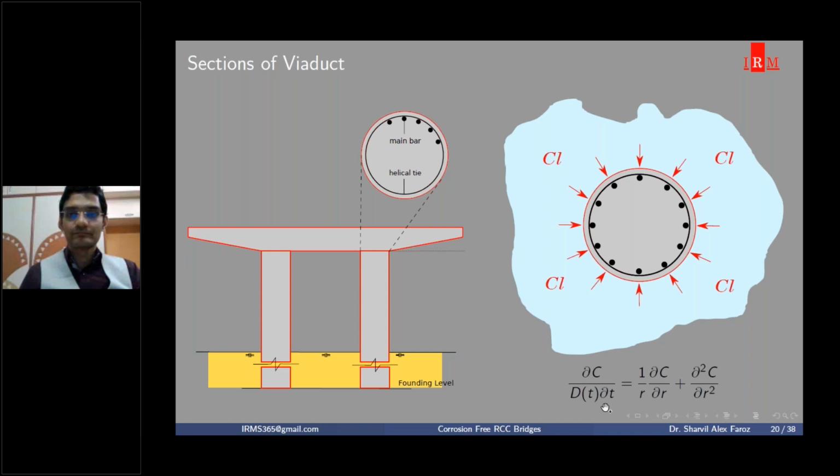So to give you a value, if I consider OPC, then generally it is around 50 to 60 years. If I consider fly ash, then it is around 30 to 35 years. So what you can understand is, if you want to simplify this D(t), then from the initiation of the project up to, let's say, 30 years, it is time decreasing, and then after that the decrease is very small. So this is how the time varying effect is considered.